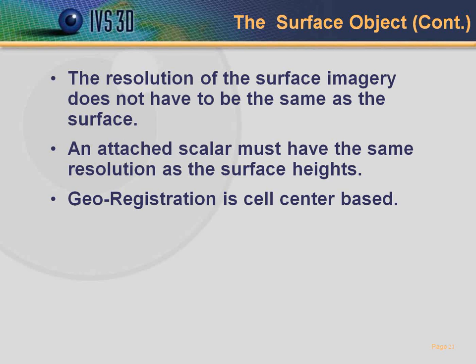And I just make a note that the georegistration is cell center based, meaning that when you load a surface and you look at the bounds, you're seeing the X range from the lower left cell center to the upper right grid cell center.